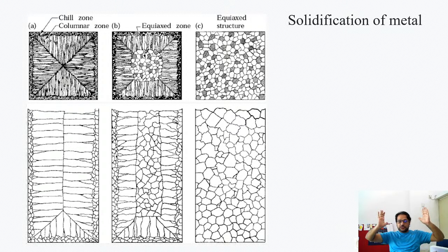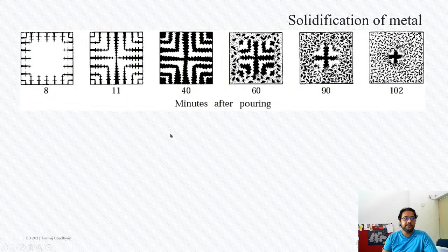If its tensile strength is stronger on one side than the other side, then the material is behaving anisotropically. So for an equiaxed grain structure piece, the mechanical properties are fairly uniform and the material does not behave anisotropically. Okay, sometimes you would want some parts to behave anisotropically, sometimes you wouldn't. That will depend on the nature of the requirement. Okay, so let's move on.